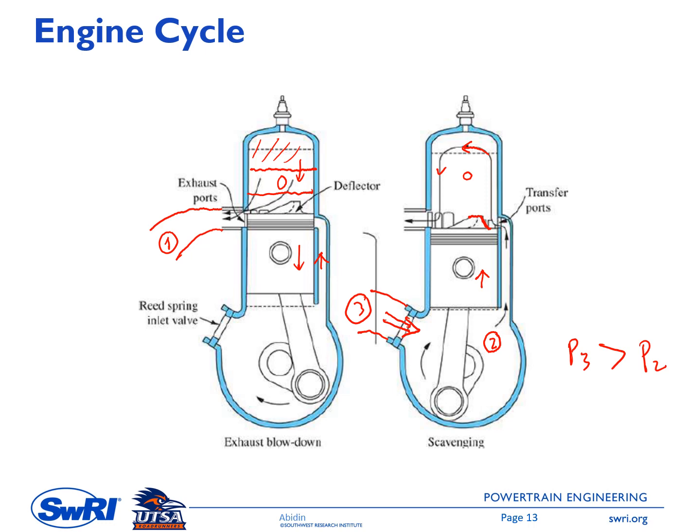The piston moves up and then closes the transfer port first, and then the exhaust port, doing a compression process, and then at the end of the compression process, either the spark will ignite or the fuel will be injected if it is a diesel case. So once again, for this 2-stroke engine, for one complete cycle, the crank wheel rotates 1 time, so it's only 360 degrees. Now you can make a simple comparison between 4-stroke and 2-stroke.